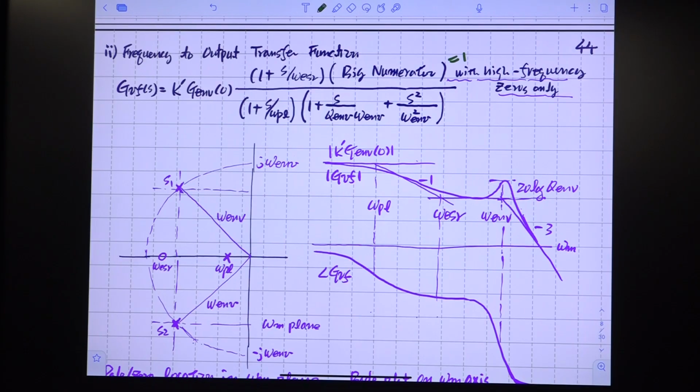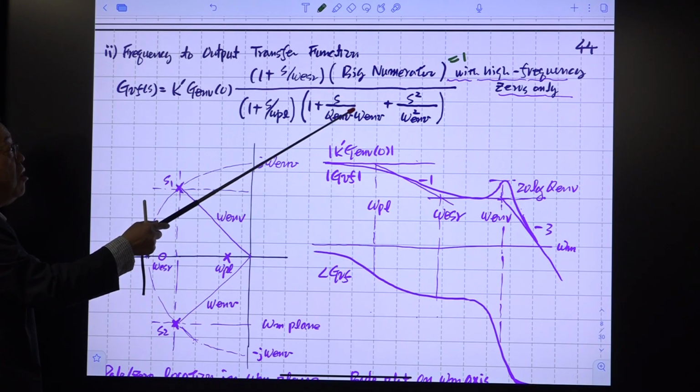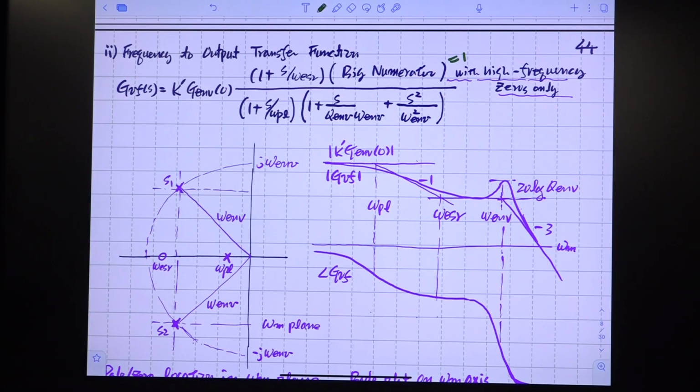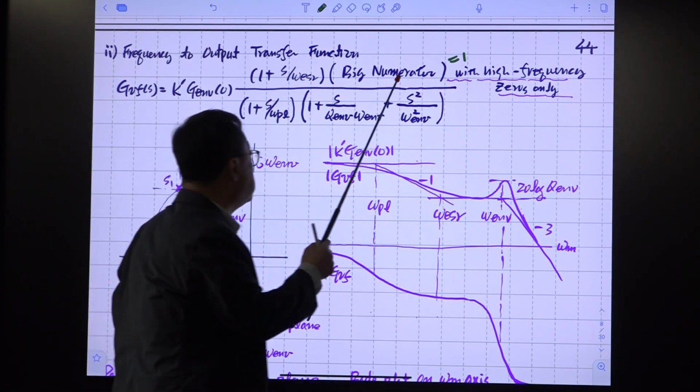And this one is just constant. This one is constant. So later on, maybe we evaluate this. This is constant. And it has this omega PL. It comes at a relatively low frequency, very low frequency. And there is omega ESR generated by the RF capacitor. A series connection of the ESR and the capacitance always generates a zero. So the zero is coming here. And this comes from this envelope, the sinusoid dynamics. You have all the knowledge about this. This is reduced to 1.